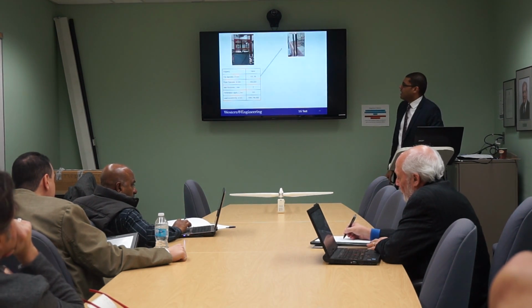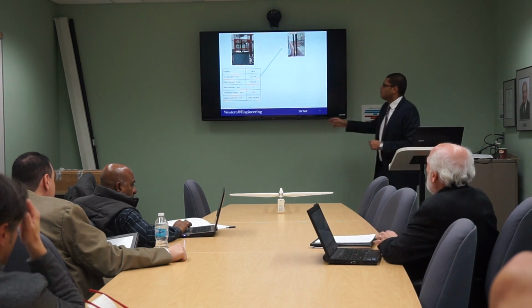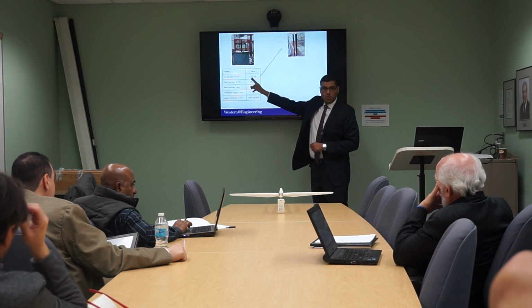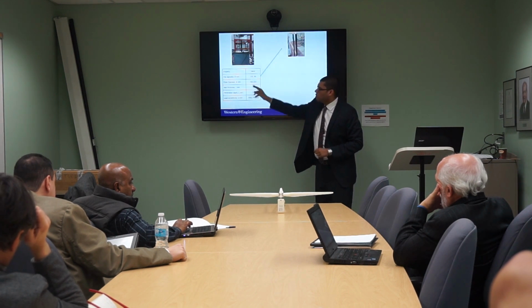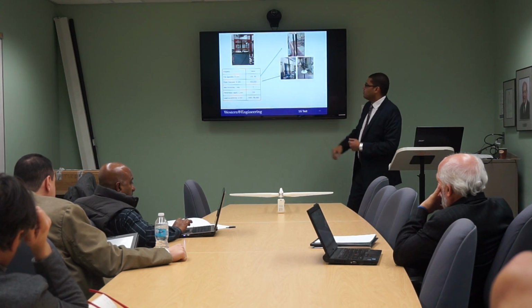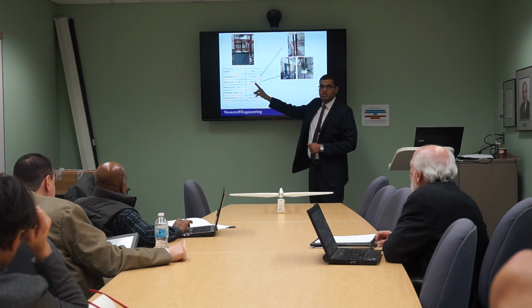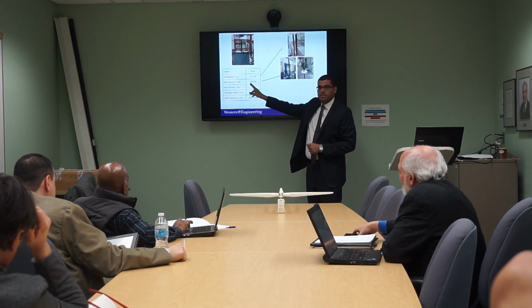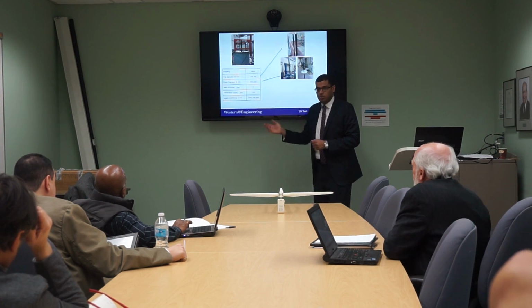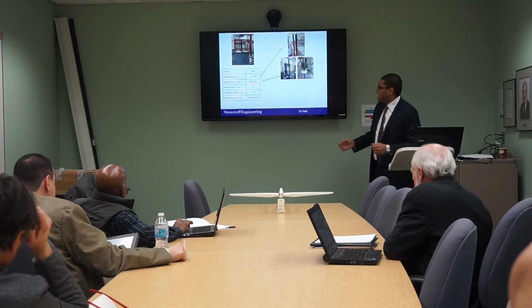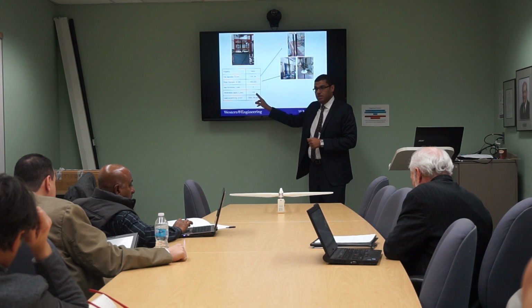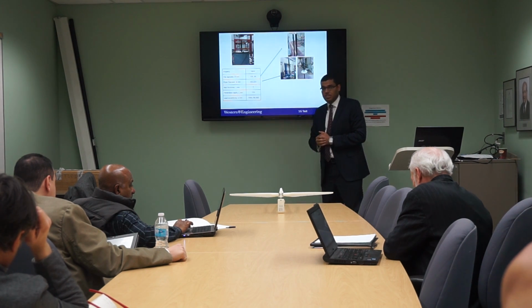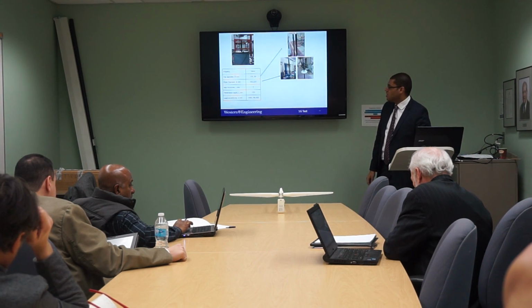In our parametric study, we use pile diameters of 80 millimeter and 120 millimeter to represent 4 meter and 6 meter diameter, and also plate diameters of 320 millimeter to represent 60 meter, and 450 millimeter to represent 22 meter. The wall thickness was 5 millimeter, and the penetration depth was 720 millimeter to represent 36 meter pile penetration.